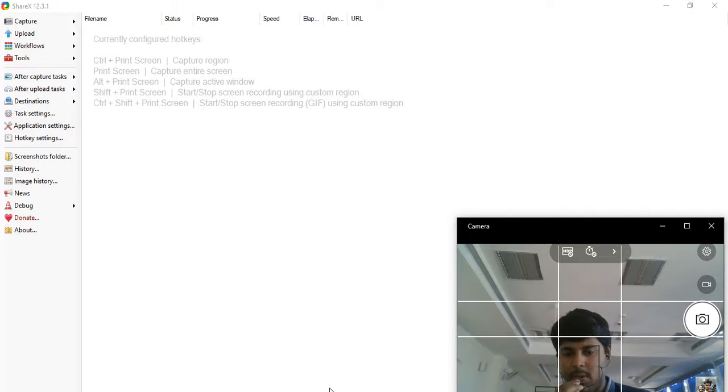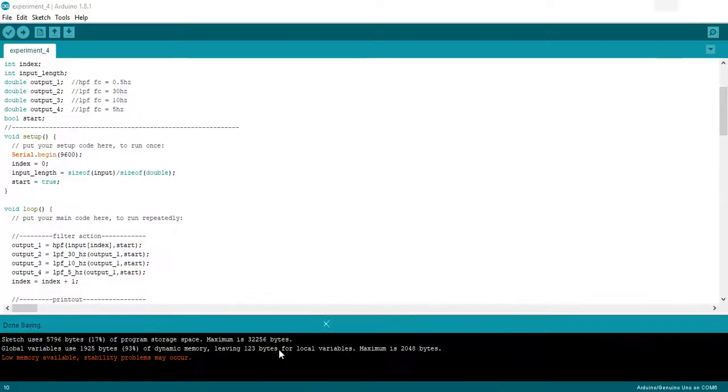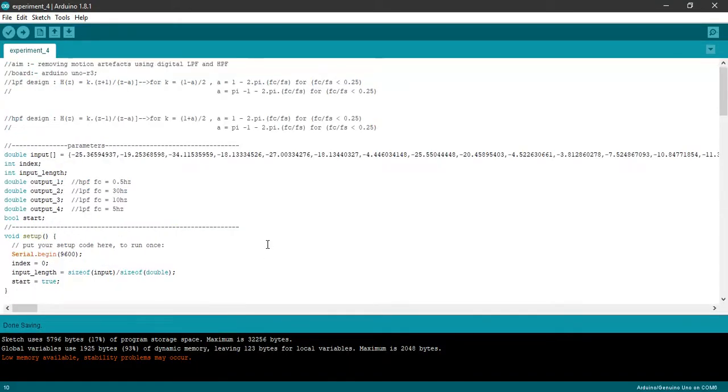Going to see how we can implement a low pass filter and a high pass filter and use them to remove motion artifacts and any high frequency noise that are present. So how we perform this is using an HPF that is placed at really close up to 0.5 Hz. We remove the baseline wandering or the power line signal that has been included into the signal. While using LPF, we can remove the high frequency noise.